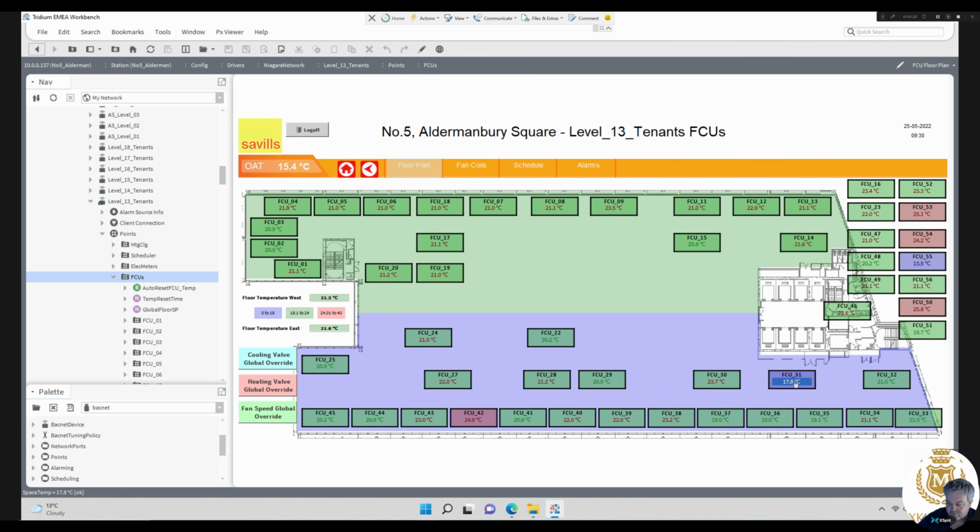We've been talking to the engineer. It's him that was on the phone when my phone rang. There's some valves in the wrong position, where you've got pin up or pin down. Some of the fan coils have come with pin down and they should have been pin up, and the valves can't be reversed. And naturally we can't change the software on this side. We've got to change it on the Distech fan coil controller, so we have to connect in there to change the software, or just get a valve that we can actually reverse a 0 to 10, and that's what we're looking at the moment.